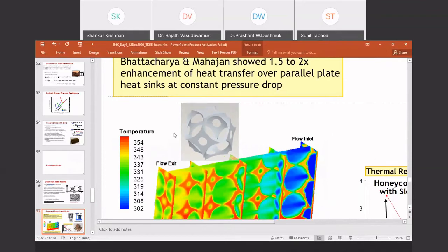So that's the unit cell. This was created by taking a cube of metal and putting spherical voids at its BCC arrangement, that is, body centered cubic arrangement. We take a unit cube and put spherical voids at its 8 vertices and one at the center. So that's the body centered cubic arrangement. We subtract that from the metal by a simple CAD operation. Then we get the structure, and that is the unit cell that we get periodically.